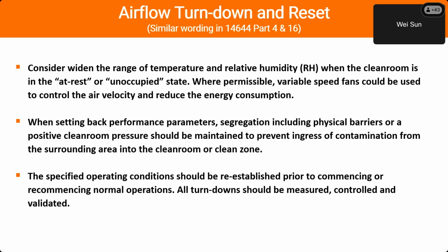So each of these rooms with a pressure control requirement, if you use a variable flow, you want to maintain the same offset. Once you turn down the supply flow rate, you want to make sure the departing airflow rate also is turned down to maintain the same. So that adds a lot of complexity for the design engineers, but that's the trend